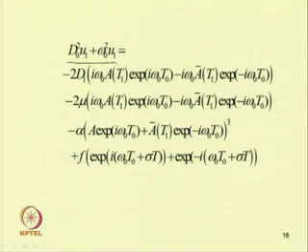So any term in the right hand side containing e to the power i omega 0 t 0 will be a secular term and will lead to infinite response. But in actual case the system is bounded, so we have to eliminate these terms, which are known as secular terms. Here one can see that this is a secular term.